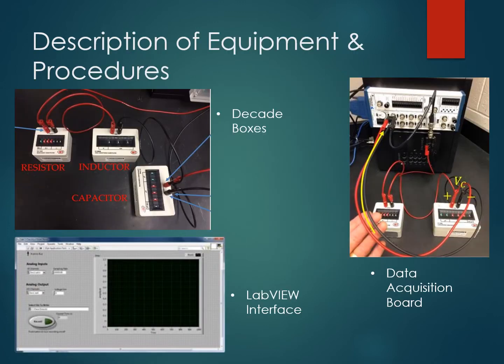The equipment used for this lab consists of decade boxes, LCR meter, data acquisition board, and a software named LabVIEW to analyze the step response. The decade boxes set the resistance, capacitance, and inductance for the circuit, which can be adjusted using physical dials.